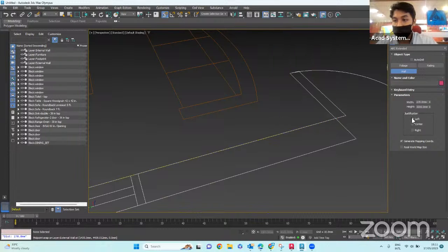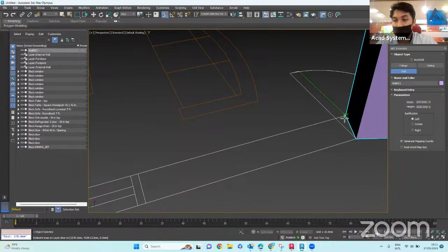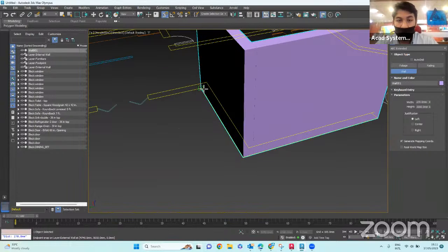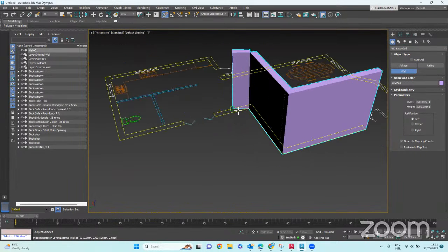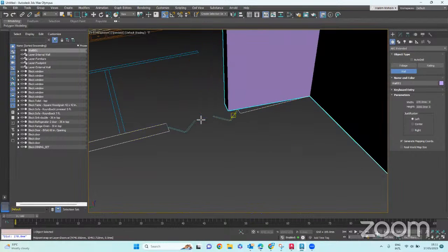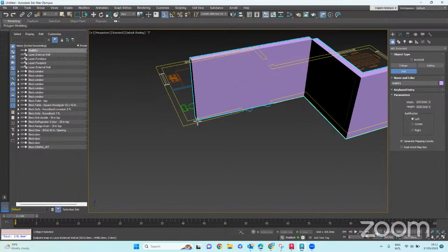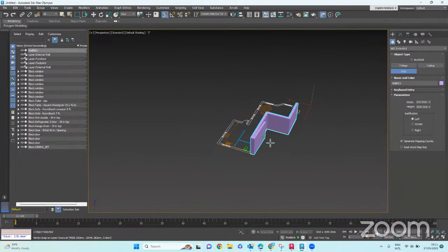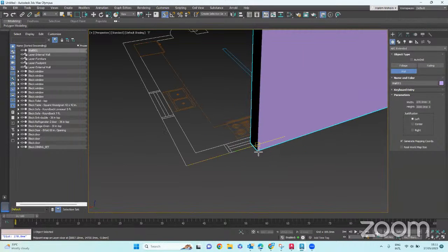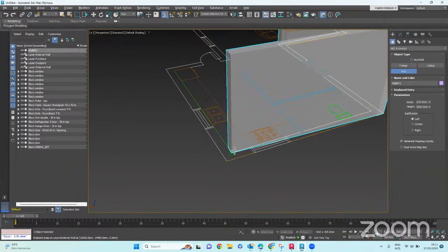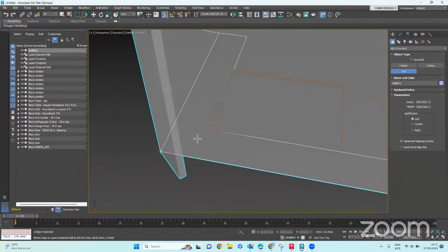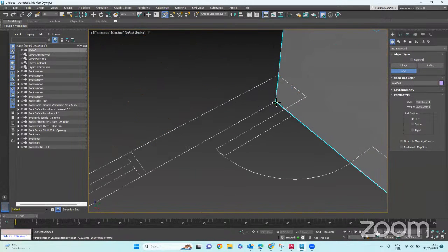So it shouldn't be there. I'm using left, it should be from here. So you can just go along our plan drawing. You don't have to stop at the door openings because that will be created automatically later. And then while creating this wall, you can also press alt X to have your wall in a half tone. So you can see the lines a bit clearer.